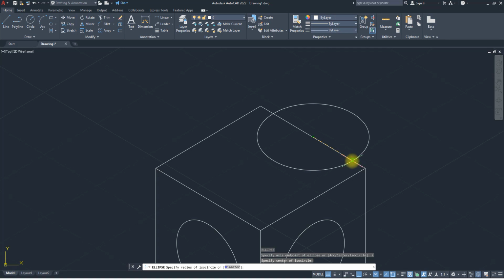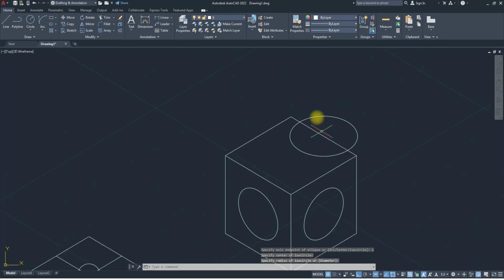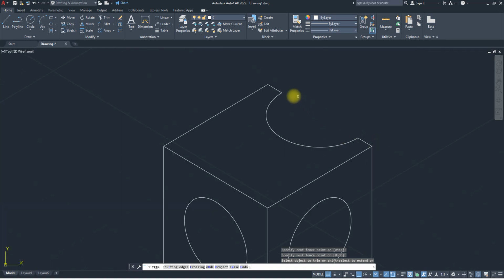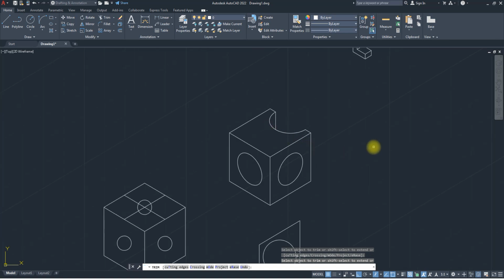So let's assume this is a chiseled radius. You notice it doesn't look like something that's chiseled. I need to trim off. So if I use my trim command, I can trim off this guy and also trim off this guy. And I have this. But that's not all. There should be a line because this place should show. So if I say my line, I need to change my view to anything that goes down. Just come down, and I can trim. So this looks more like it.